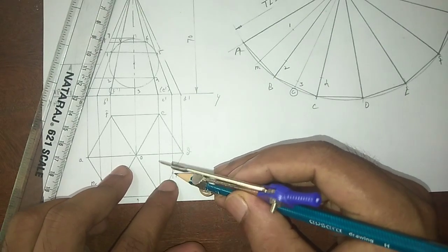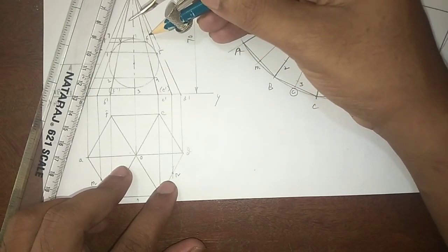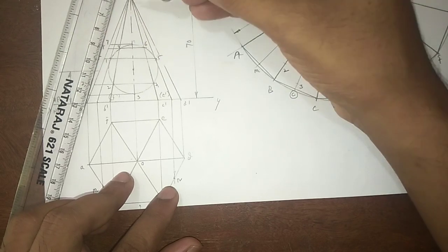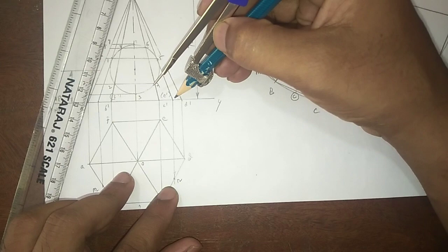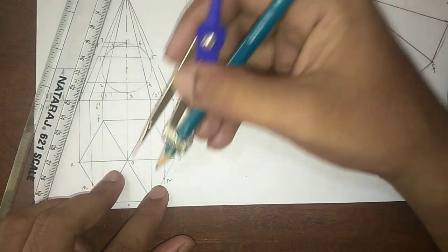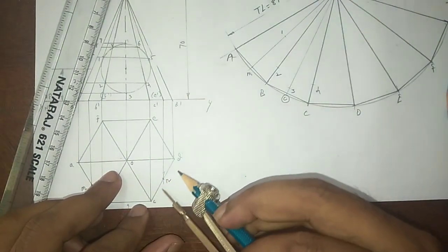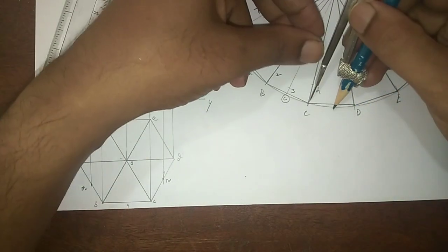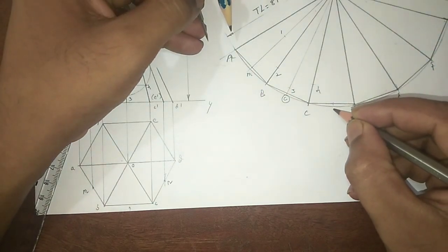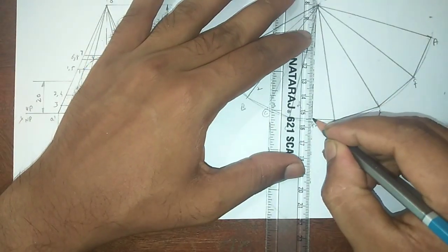Why have we located this N? This line, at first, has no slanting edge at all, it is an imaginary slanting edge. To show its outer diameter we have drawn one line from the apex point. So to bring that line here, from the base to the top view we bring the line and measure the distance C and N. N is located in between C and D. Place the compass in C and mark the point here. This is the point N. Okay, so from the N we need to draw one imaginary slanting line.